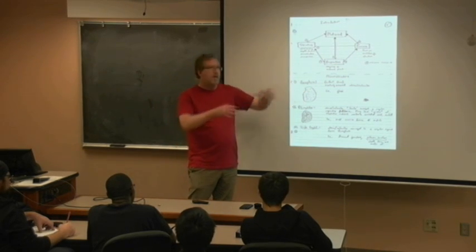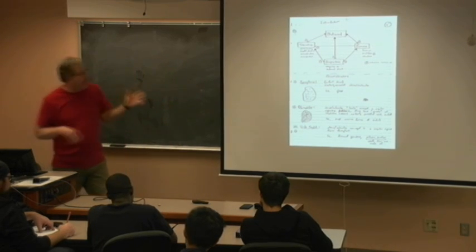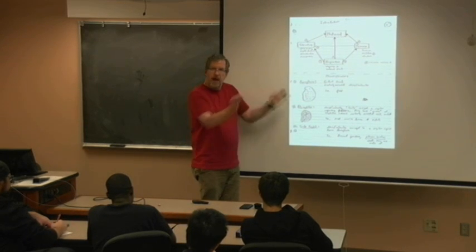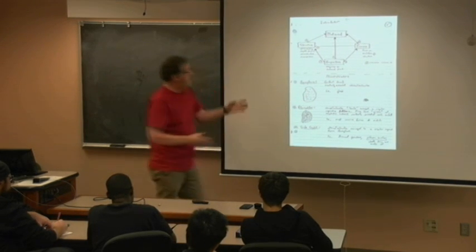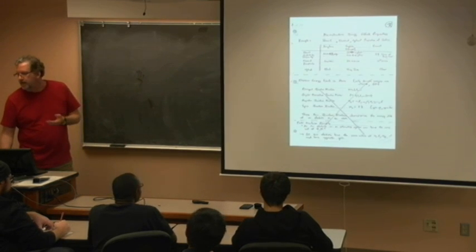The amorphous is going to be just a pea soup of confusion, and it's not going to know where to go. It also scrambles the bandgap too, because now we don't know where the atoms are relative to each other, so sometimes you kind of even lose the semiconductor properties.